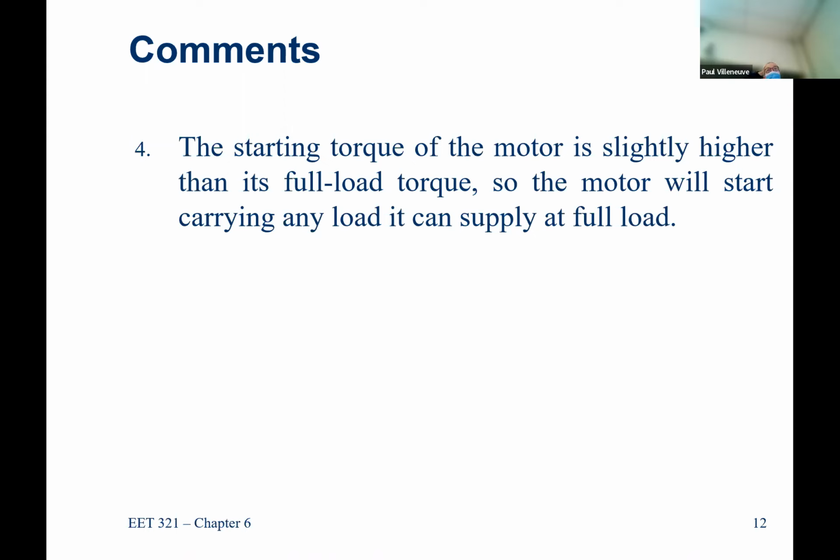So fans sometimes have special characteristics because they run under what's called locked rotor or heavy load conditions for up to a minute in some cases. Where a pump can spin up very quickly because if it's not pumping any water, it doesn't have any torque.